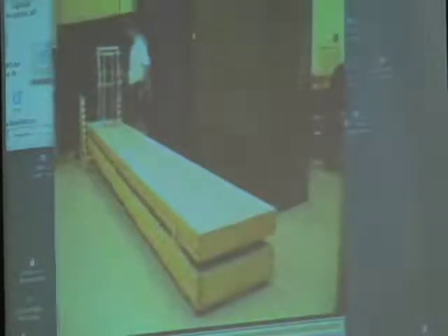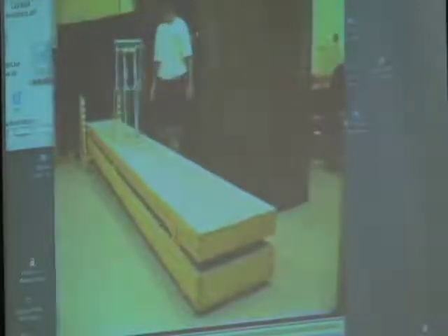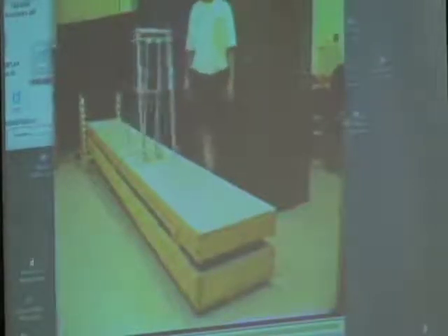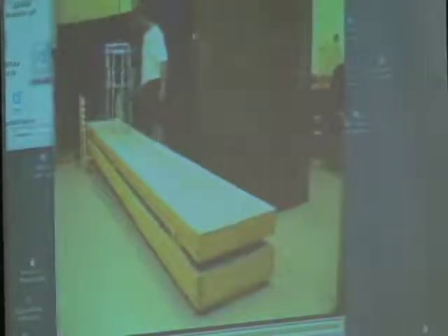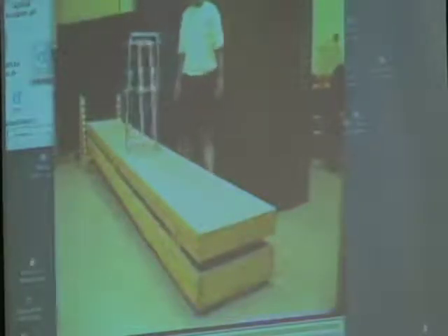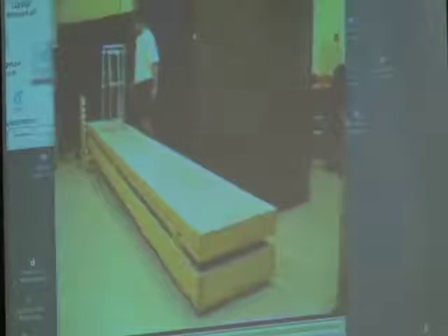Yes? You can see it a little bit by just keeping track of this height here and this height here. And this is probably something like 2 or 3 degrees. Does it matter exactly? When we do computer simulations of this, less than a certain slope it won't walk, more than a certain slope it won't walk. In the lab we pick a slope where it seems like it works pretty well. We have designs which on the computer can walk on arbitrarily small slopes, and the smaller the slope, the slower it walks.